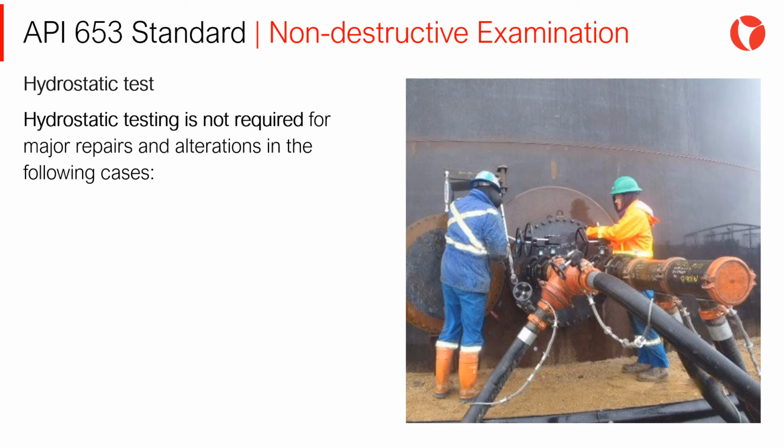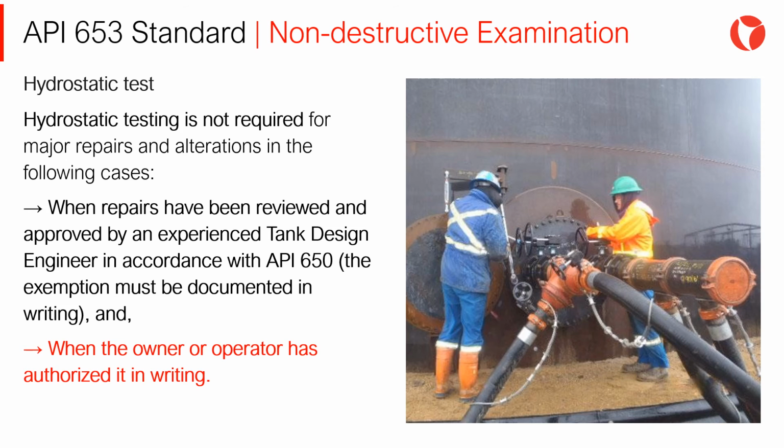On the other hand, hydrostatic testing is not required for major repairs and alterations in the following cases: when repairs have been reviewed and approved by an experienced tank design engineer in accordance with API 650, the exception must be documented in writing, and, obviously, when the owner or operator of the tank has authorized it in writing.